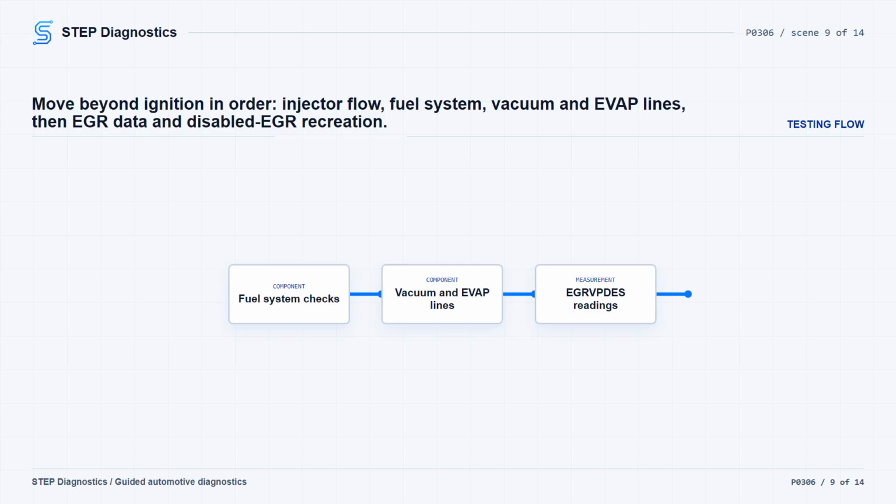Next, follow the fuel system diagnostic path. If a fuel concern is found, repair it. Clear the PCM DTCs and repeat the self-test. If no fuel concern is found, inspect the vacuum hoses for damage, deterioration, or restriction. Some vacuum leaks can be heard. Also inspect the EVAP lines and hoses for wrong connections or damage.